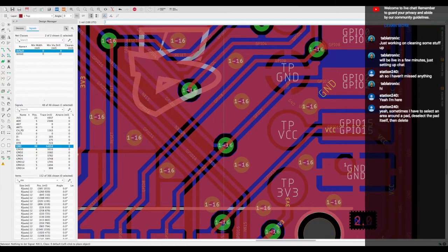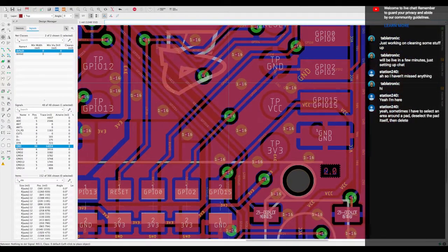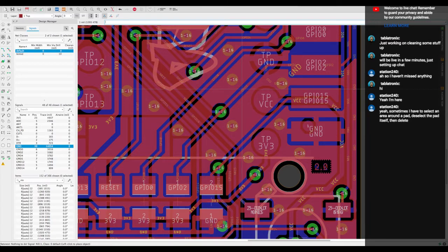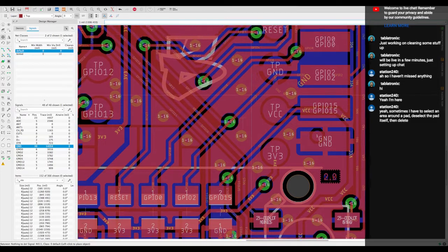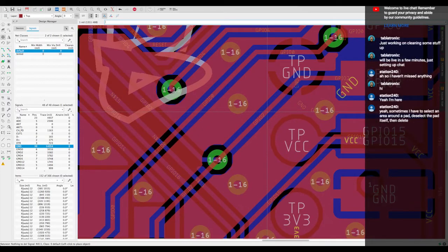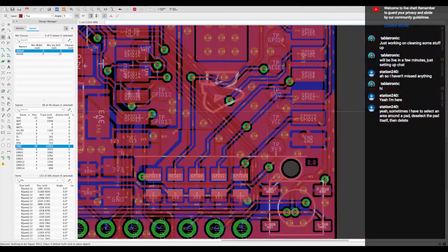But this down here shows you whether your annotation is synchronized between your schematic and your board. Sometimes that can get broken, but not for any real reason. So what I do is I'll close out the schematic, let them unlink, and then I'll fix it all up, delete stuff and re-add the traces right back the way they were. Then I'll reopen it and relink them together, and they should link right back up if nothing was changed. Sometimes you just got to do that to clear whatever the stuck state was.